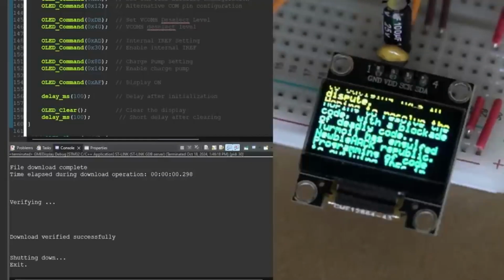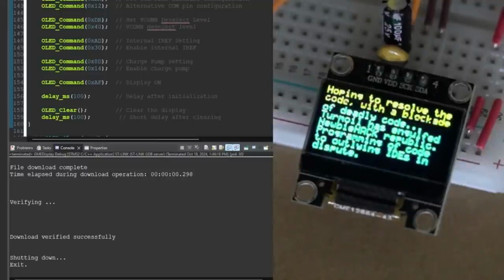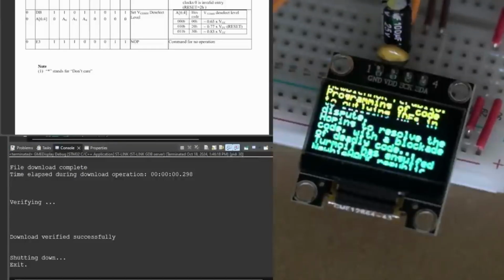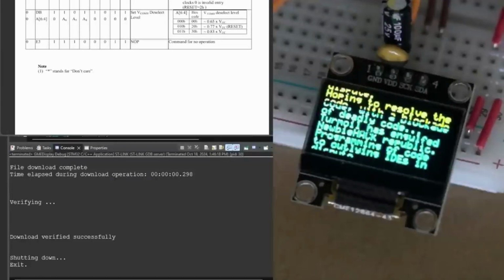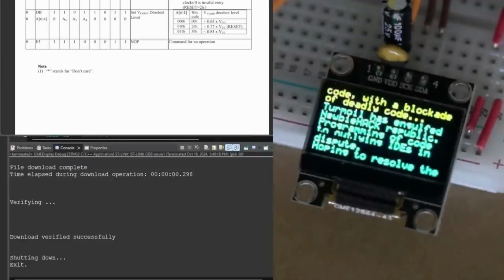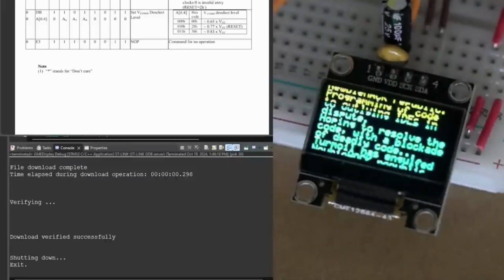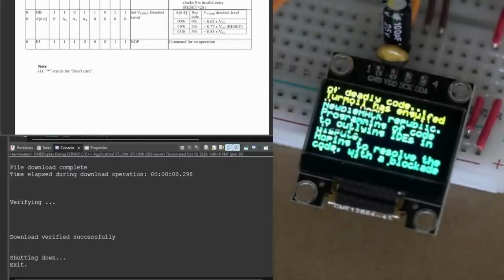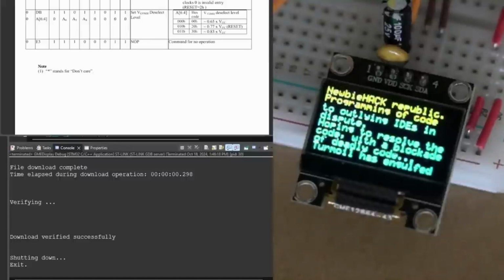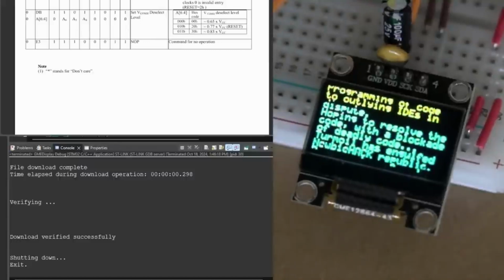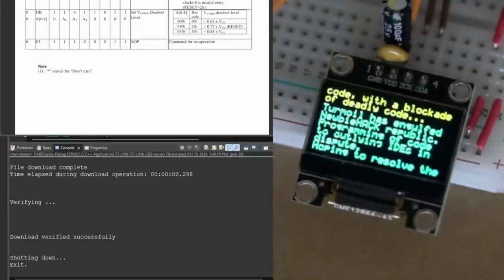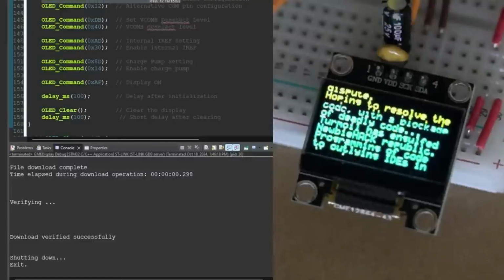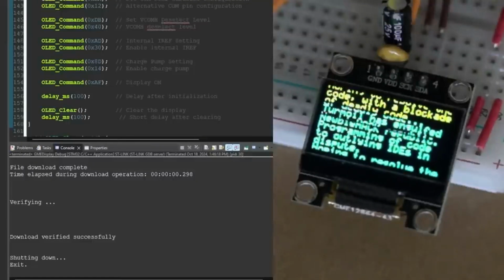Oh, interesting. So the last 3 sets D, so it's used in combination. Okay, I totally overlooked this. +1. Okay, so this is the prescaler. This is like a prescaler, and then this sets the oscillator frequency. So you have to use them in combination. Well, we could look at every single value between 0 and 255 and see what happens.